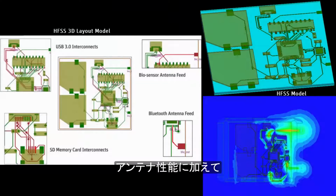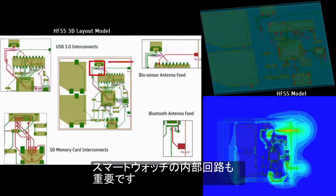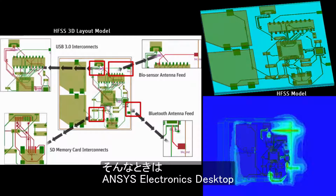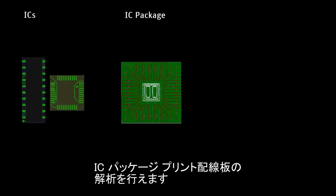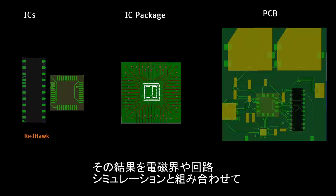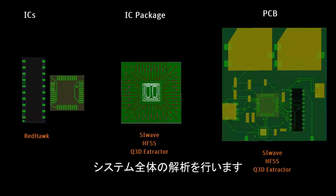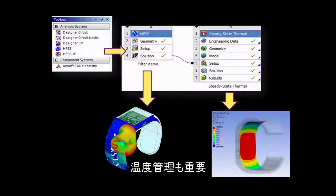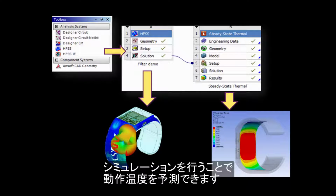In addition to the antenna performance, we need to look at the electronics within the smartwatch. Using ANSYS Electronics Desktop, you can perform analysis from IC to package to printed circuit board. ANSYS Apache tools like RedHawk are used for the IC modeling, and we couple those results with electromagnetics and circuit simulation to analyze the full system. As you vary the signal speed, you can determine the robustness of the design. The watch must not get too hot, and simulation can be used to predict the operating temperature.